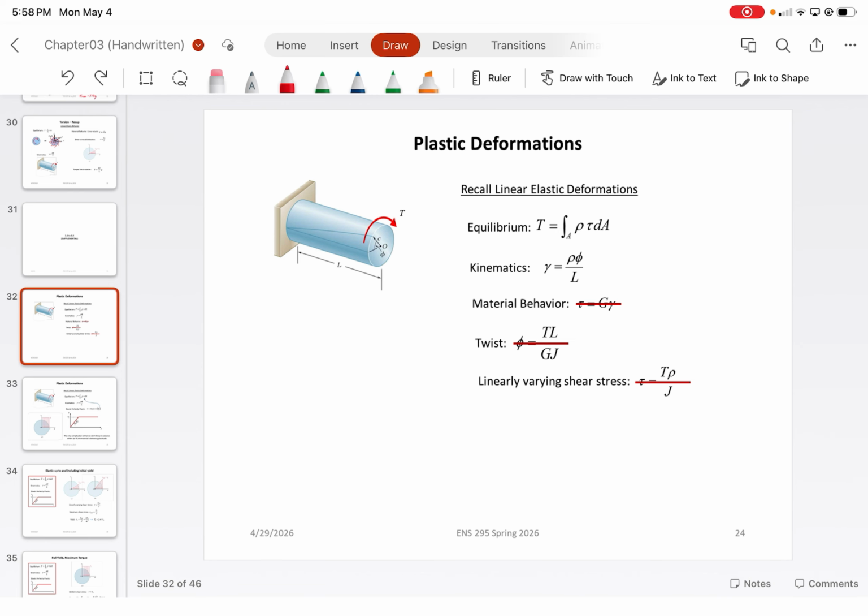All right. So as we learned, equilibrium is just the sum of the shear stresses times their areas times the moment arm of each area. We can apply kinematics, but as we have already seen from the material properties, once we reach plasticity, guess what? Hooke's law doesn't apply anymore, right? Because the material has yielded, which means if you're assuming an elastic, perfectly plastic model, then on our stress strain curve, if that's tau and this is our strain, then we can't assume Hooke's law.